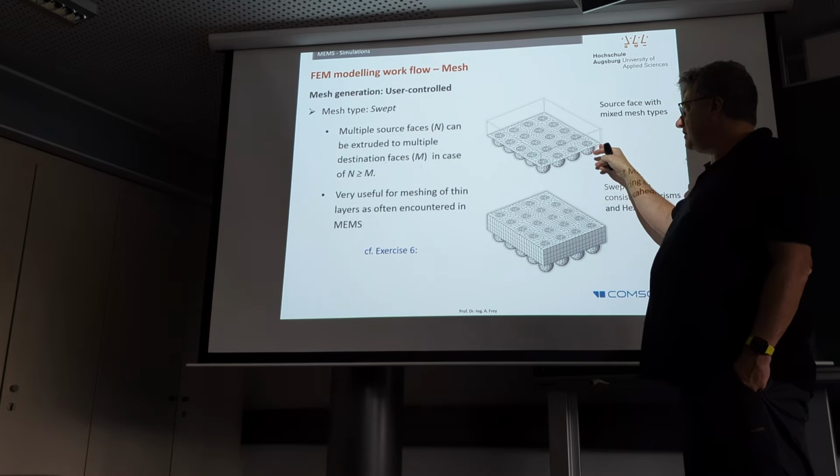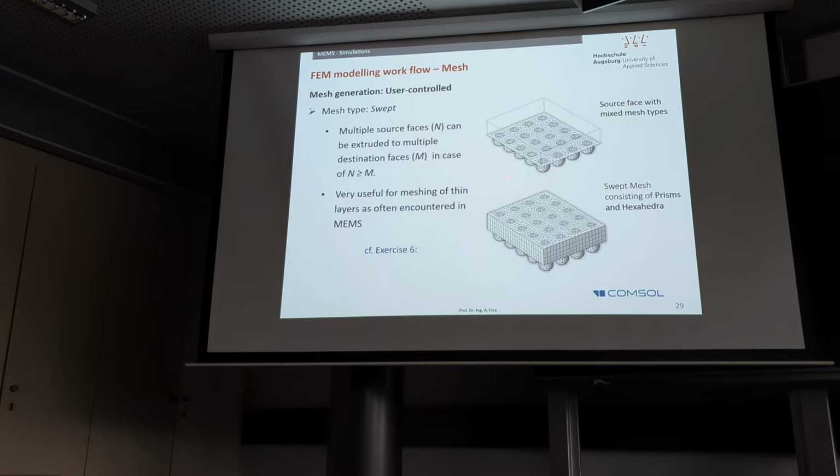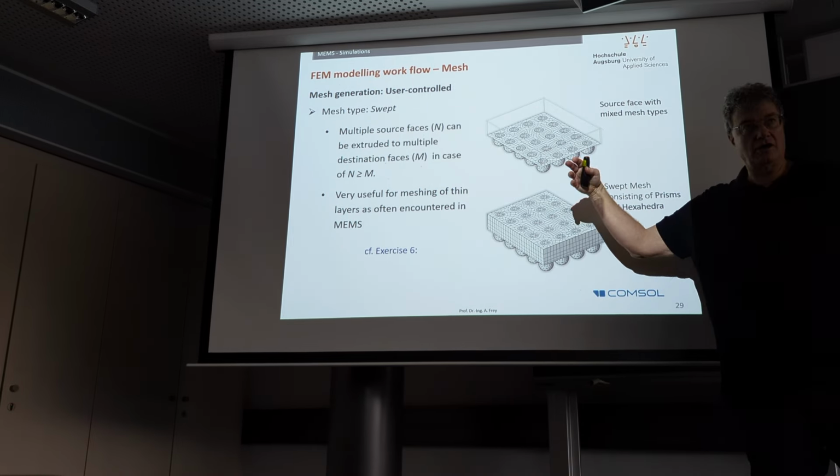If you have a situation with an array, so this is an example, I think it's from a chip, from an integrated circuit, and how to connect that integrated circuit to a printed board. So one version is with this technique. Packaging is a cost factor, so people came up with such a solution where you have pads on the chip and you have pads on the printed circuit board, and then you need to put some solder balls there and to heat it.